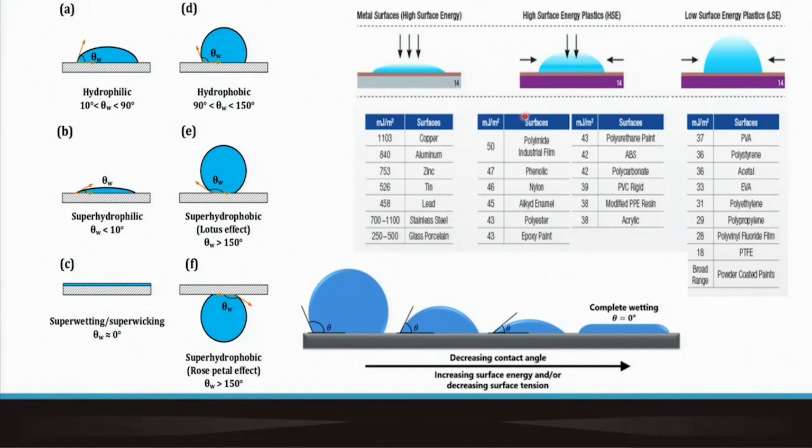But what we have to be careful about is to understand how we measure the angle. And that's where we cannot afford to make a mistake. So in a situation like this, we are showing certain thickness here, but actually imagine this thickness is negligible. So you can't define where your tangent is. So the tangent actually will be in that case parallel to the solid substrate, and hence the angle subtended will be near zero. So that's complete wetting, the extreme, super hydrophilic.